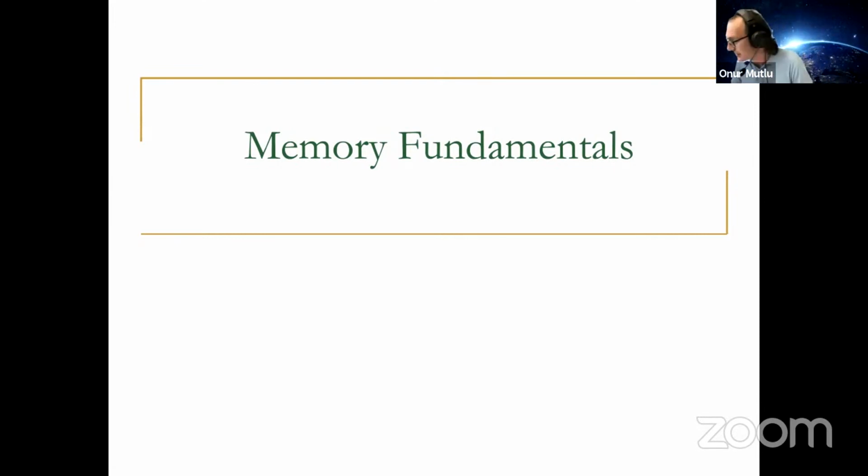Okay, are there prospective alternatives to the memory cell implementations we covered, which could increase speed, like liquid crystal-based stuff? Certainly, there are potential emerging technologies. Actually, I'm going to end this part of the lecture with some emerging technologies. But unfortunately, many of them are slower than DRAM and SRAM. That's the unfortunate part. So speed, in terms of the latency of the cell structure, we don't really have a whole lot of materials that we know of that are faster potentially at this point.